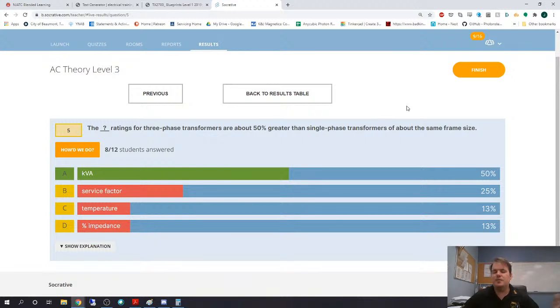That's because in 3-phase, the sine wave never hits 0. The phases are 120 degrees apart, so it's always riding on the highest phase at the moment. The individual phases drop past 0, but that doesn't matter to the motor. It's always being pushed, as opposed to a single phase motor that is pushed intermittently.